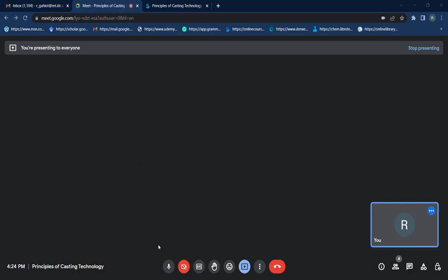If you move to problem number eight, which of the following has the maximum ductility? I think this is also an easy problem. Malleable iron, sir. Yeah, right. But here, sir, one category is not mentioned. Which one? Ductile iron. So which one is better in terms of ductility, ductile iron or malleable iron?